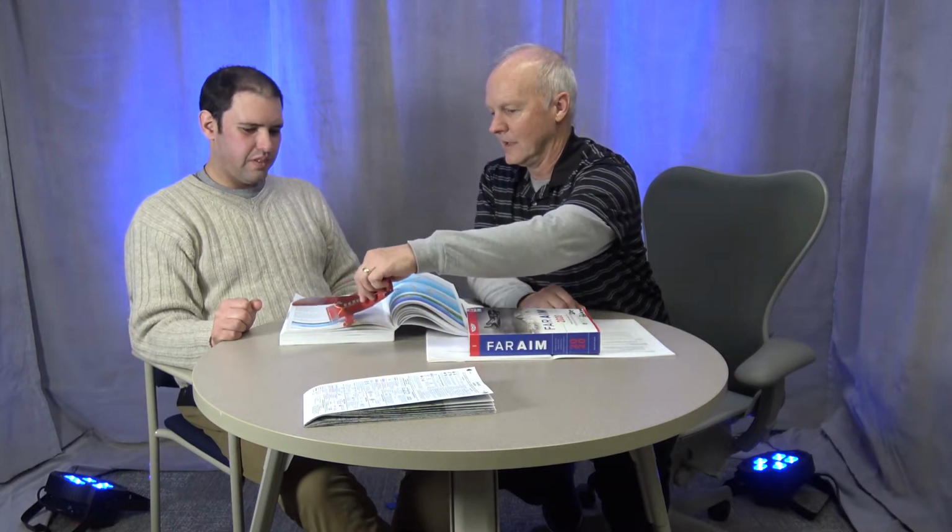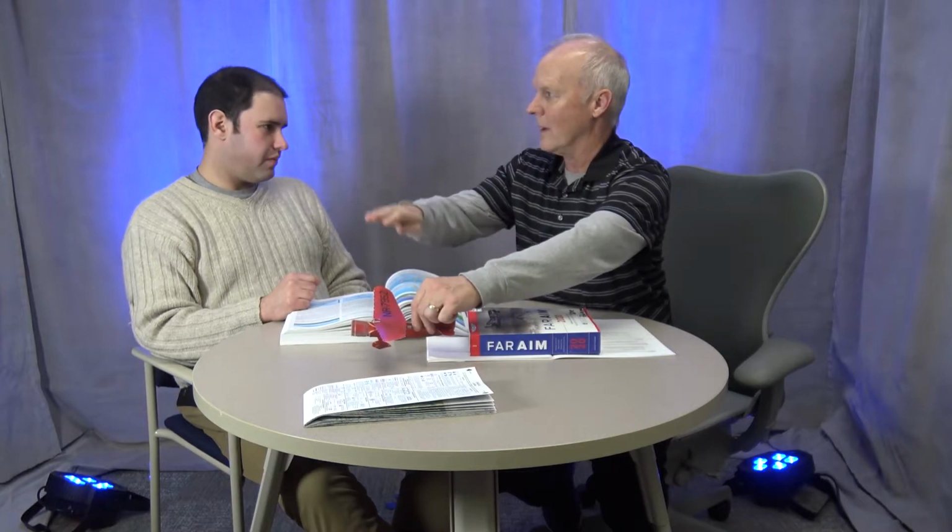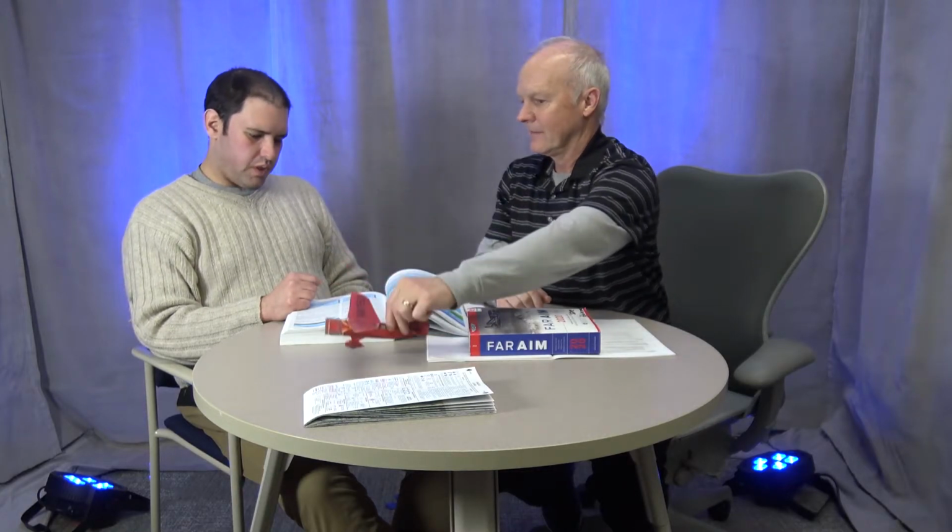Exactly. And if you keep trying, you just pretty much float back down to the ground. I remember reading in there, you get off and you get in ground effect and you stay there while you pick up speed. If you pop off the ground too quick, keep the nose down and get your speed up until you're well past that. That's when we're taking off on short runways. We want to pop the airplane off the ground as soon as we can, so you don't have the friction and you can pick your speed up quicker.